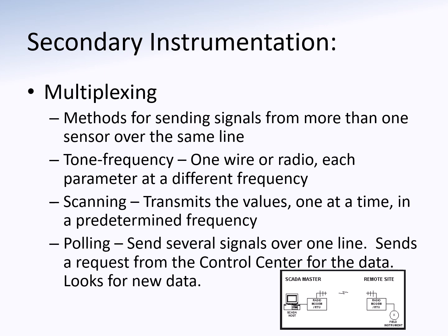Polling is what I'm most familiar with. That's just what our SCADA system uses. Basically, it's just constantly sending out a signal to each facility and requesting the information that it has. We have multiple sites and it's constantly pinging them saying, "Hey, what new information do you have?" And so it can take a couple minutes for that information to come in. But that's the idea of how it's working.